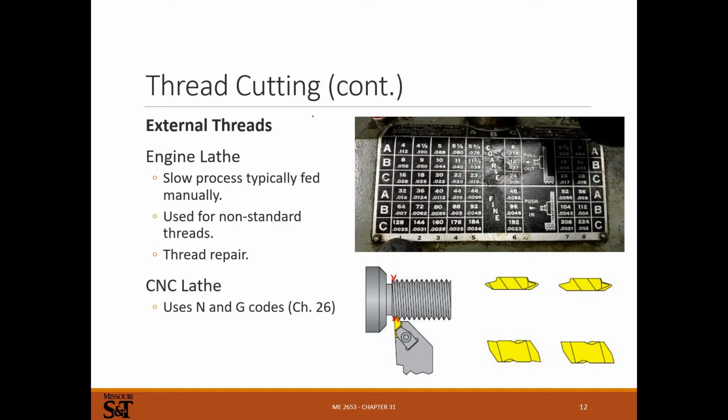And there'll usually be this little rotary dial that will have different indicators on it, like 1, 2, 3, 4, and there'll be some stationary thing, and this thing will spin keyed to the angular velocity of the lead screw, and there'll be some kind of a clutch. And so if you start this first pass with start 1, you're going to machine down to here.